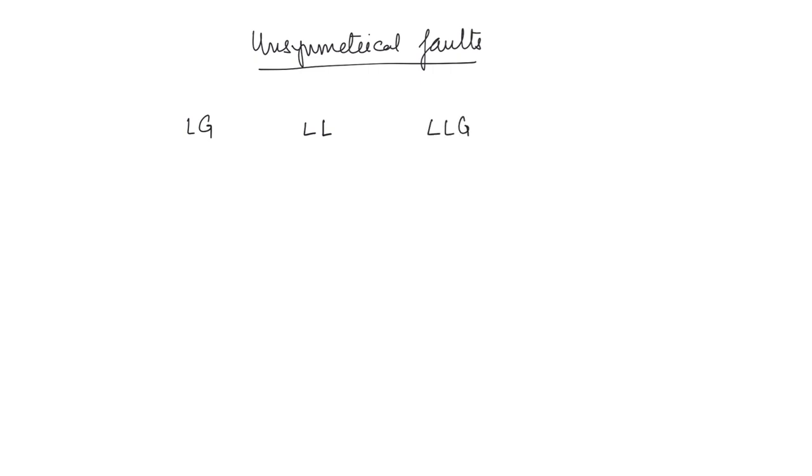So now that we have got an understanding of the symmetrical components, we can analyze the unsymmetrical faults. Right? So first unsymmetrical fault is the single line to ground fault, LG fault it is called. Another unsymmetrical fault is the line to line fault. Two lines are short circuited. And we also have the double LG fault. So all these three are unsymmetrical faults because they are going to induce imbalance into the three-phase system.